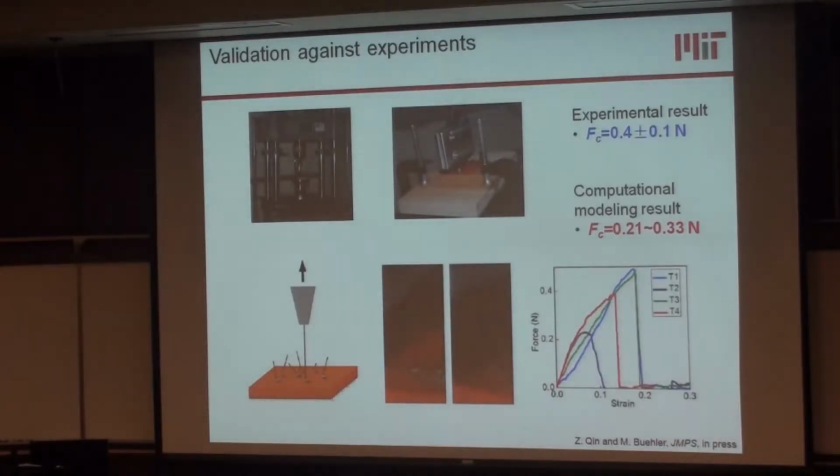And we do the tensile test for each of those single fibers, and we observed that the average detachment force is 0.4 plus or minus 0.1 Newton. So the simulation results combined with theoretical predictions have a good agreement with the experimental results.